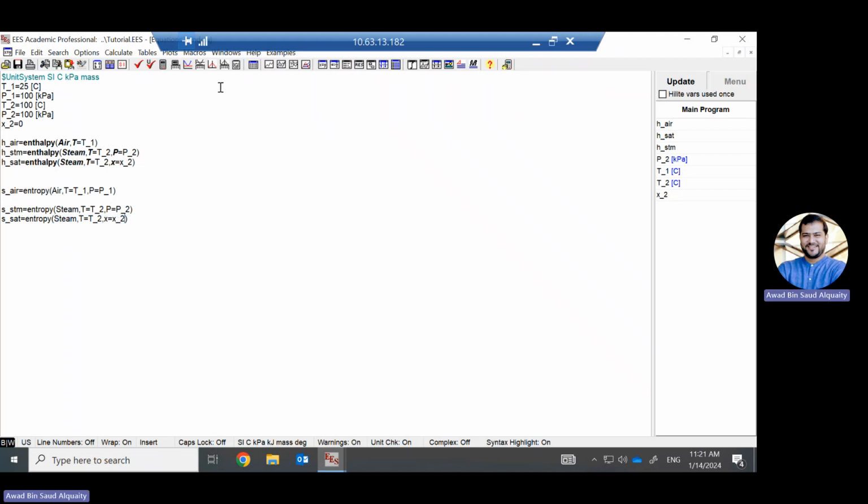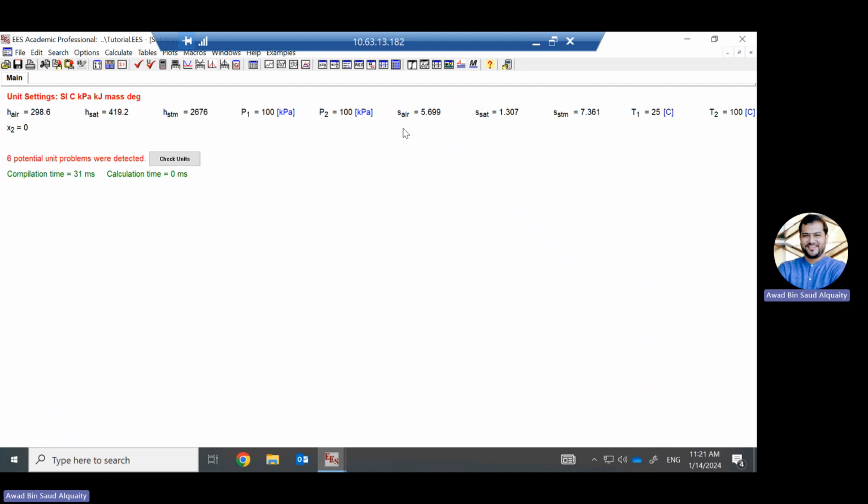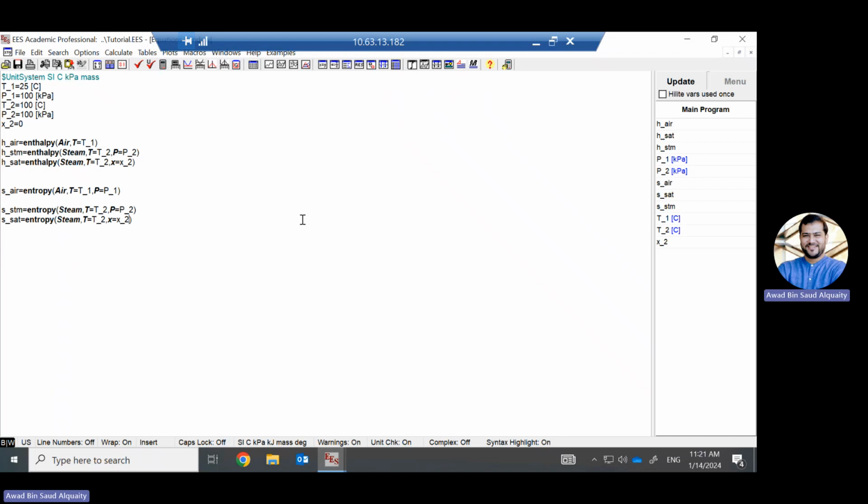Here, you can click this; this is an optional step. You can click this just to see everything works out, everything is as per your wish, and this is exactly what we want to get. Then just click Calculate, and you get enthalpies and entropies at the desired state. So that's it. It's as simple as that. You can use this for writing further equations and go on and solve it. The key point here is that on the right hand side you should have a known value. You cannot put an unknown on the right hand side. That's how it works. It also does some iteration. So it's a very useful tool, very useful software. We'll use more of it when we solve examples in the class.